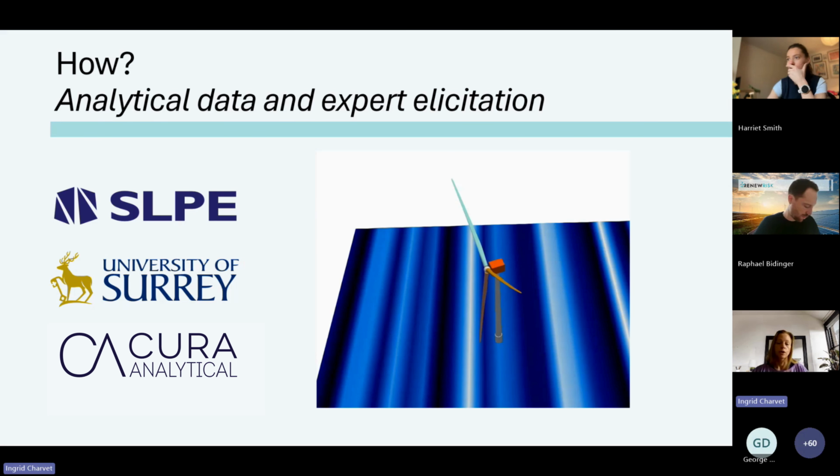So these Monte Carlo simulations, essentially, consist of running specialist software, a finite element software called Abaqus, thousands and thousands of times for a number of small variations of uncertain parameters, such as the nacelle mass and the diameter of the jacket legs, if we're looking at jacket type turbines. Things like the number of bracing systems, etc. So we vary these parameters to have some uncertainty and obtain a cloud of thousands of data points to which we can then fit a model.